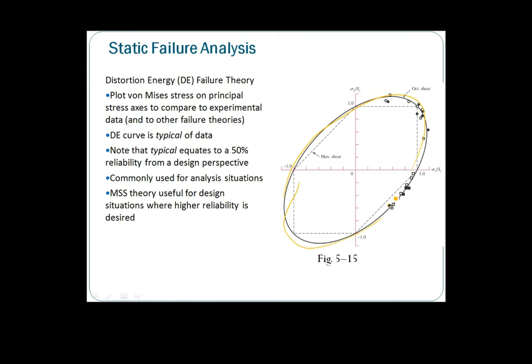Whereas MSS theory is slightly more conservative. It predicts failures earlier, at smaller values of principal stresses, compared to DE theory. So for analysis, we use DE theory; for design, where we need more conservative theories, we use MSS.